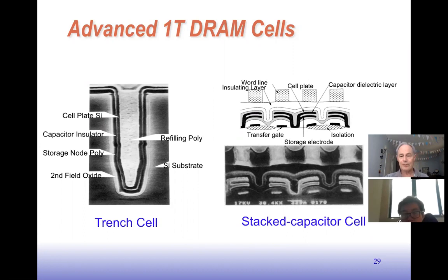The other thing I should mention is the DRAM chip manufacturers like to make them as cheap as possible. So they add some processing steps to help make the DRAM capacitors, but they also take away some of the extra steps that are used more effectively for logic. And in fact, some wouldn't even have P-type transistors. They might only have N-type transistors to save on processing steps.